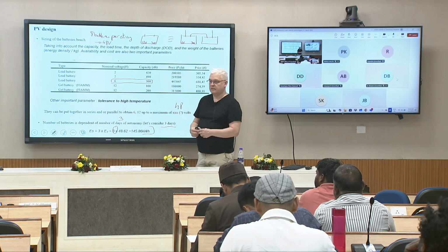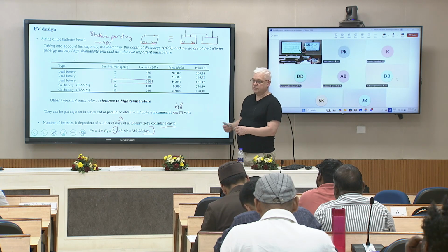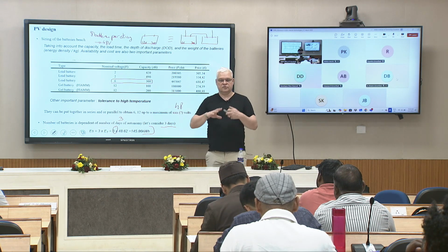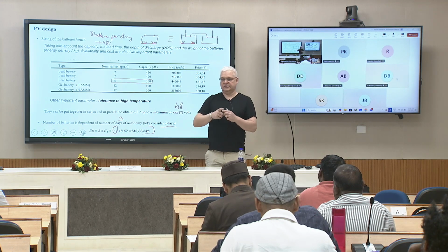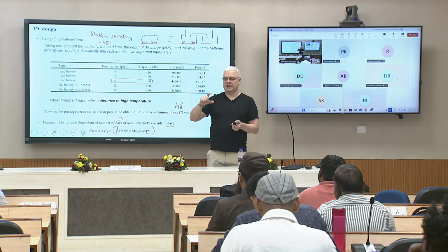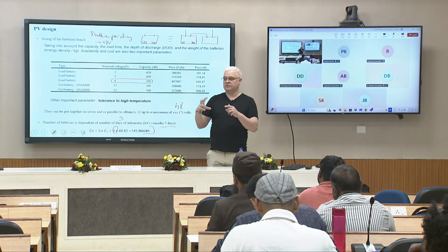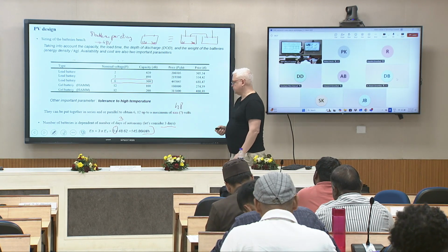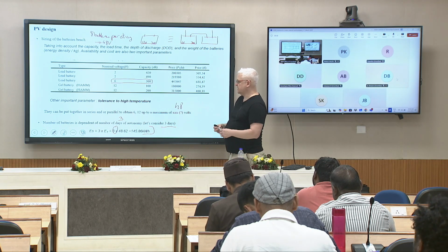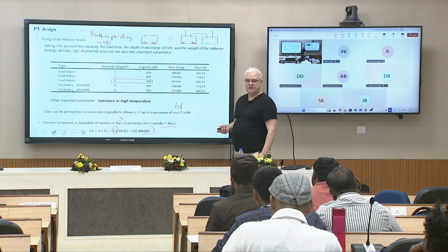While selecting the voltage, do we need to see the specification of the inverter? Yes, the inverter has to be consistent with the global power of the central, because the inverter helps to find the maximum power. It is tracking the maximum power, so it has to be consistent with the global power of the PV central. Also, the voltage has to be taken into consideration, but it is the maximum power that will help to design the inverter.